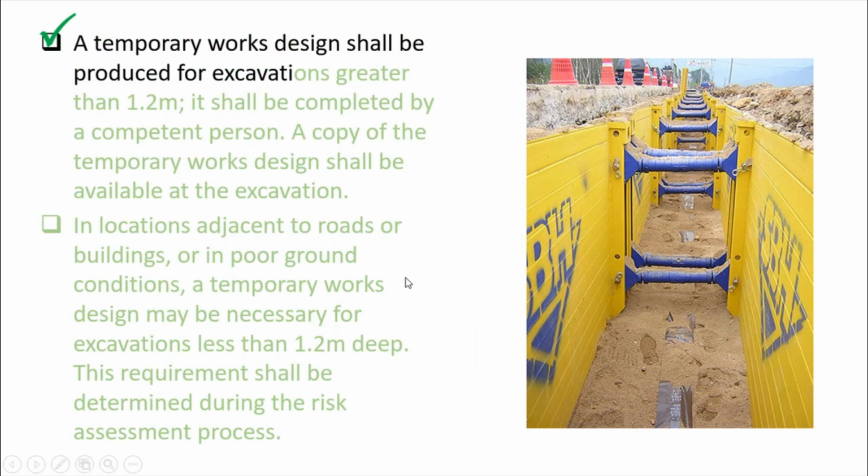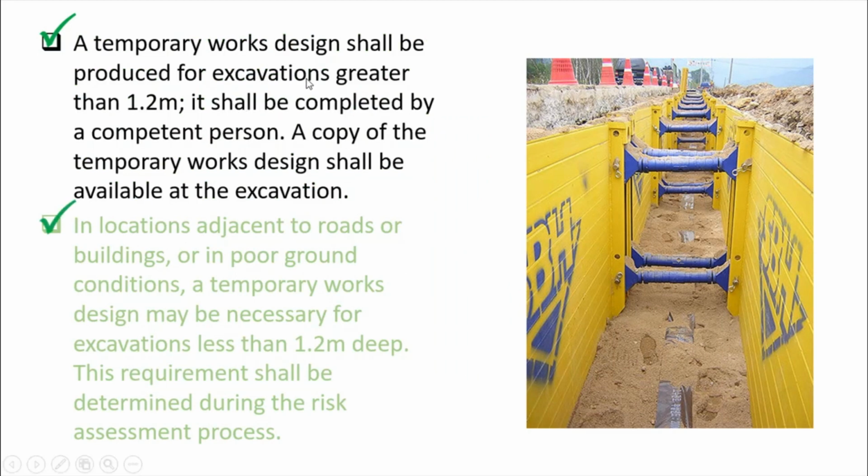A temporary works design shall be produced for excavations greater than 1.2 meters. It shall be completed by a competent person. A copy of the temporary works design shall be available at the excavation. The competent person they are talking about here is, for example, the structural engineer. He can make a design on how the excavation will be prepared if the excavation is more than 1.2 meters in depth.